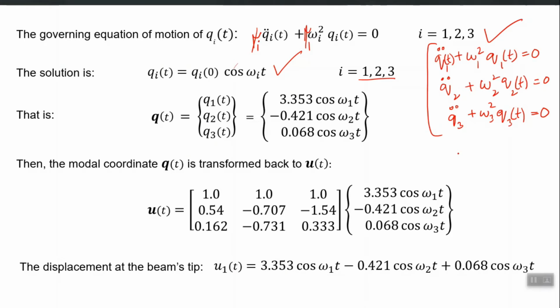In our case, q dot of 0 is 0, and q of 0 is given by 3 numbers which are shown in the last slide, q of 0 vector. So we know what is q1 of 0, q2 of 0, q3 of 0. So the initial displacement for all 3 equations is given. The initial velocity for all 3 equations is all 0 0 0, right. So we can apply now, because now let's take out one equation. We have the free vibration equation for a single degree of freedom system, and the initial displacement and initial velocity are also available to us in q coordinates.